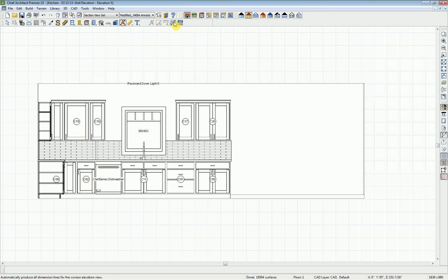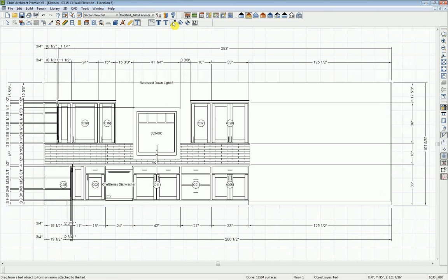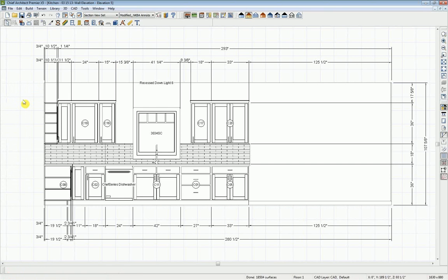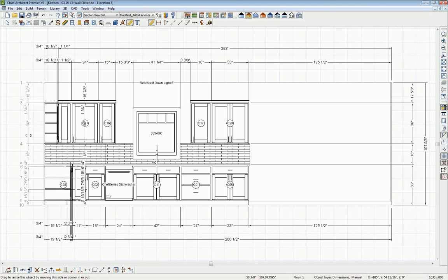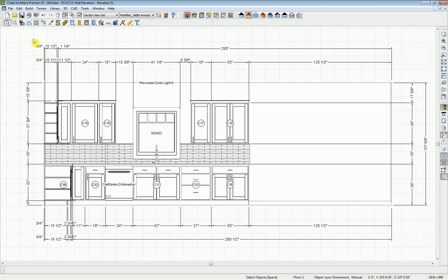In our dimensioning tool, we have an auto elevation dimension. So with one click, it will just dimension everything for us. So we can get in here, we can single click on specific items and delete those if you want to. You can also get into your own manual dimension and manually dimension that out. So we can just click and drag a line right through to pick up our elevation and drag it over. So you will see these diamonds. Those are the little indicators here. We can just click that diamond and drag it right off. So it's locating to the cross section of my cabinet and all of the shelving. So just click and drag those off if you don't want to see those. Alright, so I'm just going to send this to my layout.